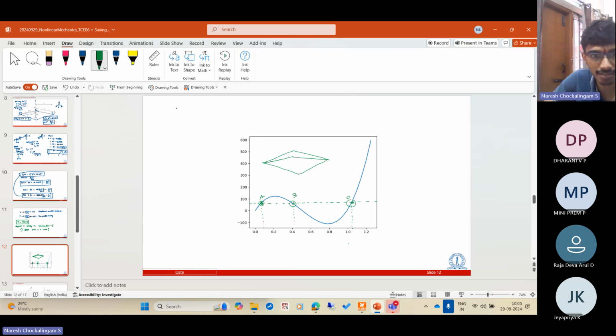If the structure is linear, what do we do in this matrix analysis? We look at the element stiffness matrix, transform it, get the global stiffness matrix, and after getting the global stiffness matrix, we get a system of equations, F is equal to Ku. So ultimately, what we have arrived at is, given U, how to find F. When we do the assembly of the global stiffness matrix, that is what we do. But getting U given F is very simple because U is just K inverse F.